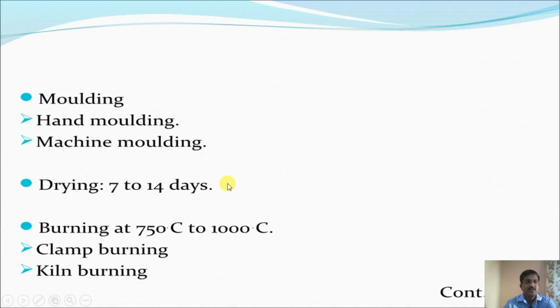Drying of the brick is for 7 to 14 days, and thereafter burning is carried out at 700 degrees Celsius to 1000 degrees Celsius.